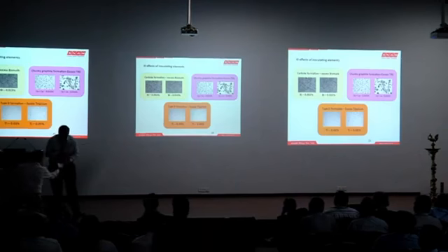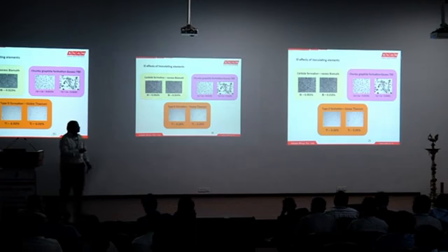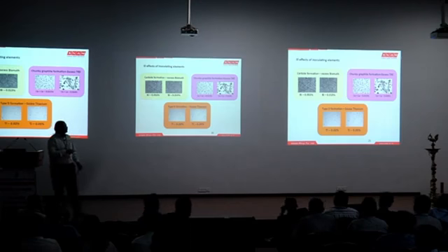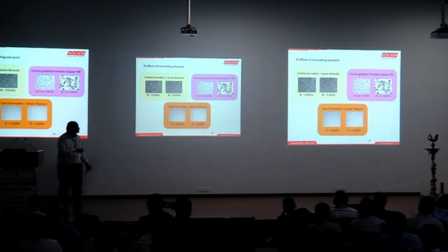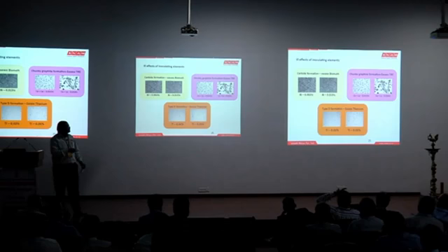I've come to the last slide. These are the ill effects of inoculating elements. What happens when you overdo your inoculation? It's overdosing. Too many sleeping pills will take you to the forever sleep stage. So excess of cerium, lanthanum, excess of bismuth, excess of titanium have ill effects of their own, the individual elements' characteristics.